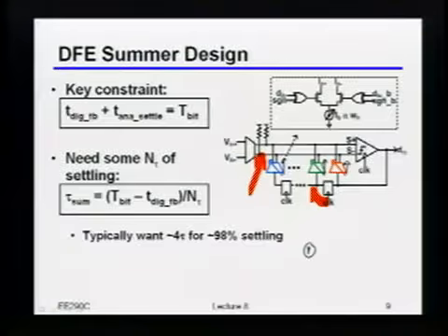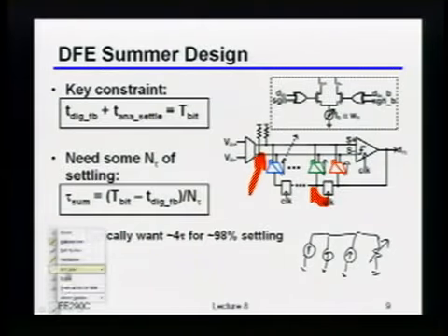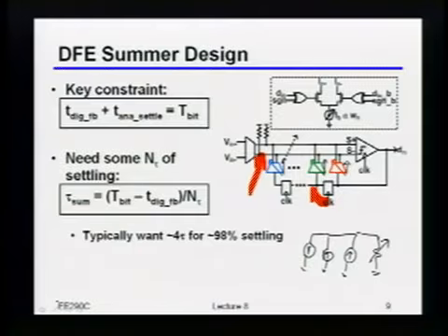So I can take all of those currents and dump them all into some node, but all that nonlinearity is doing is modulating that resistance, right? In other words, the addition itself, because that's all happening in the current domain, is linear. The only thing that's nonlinear is converting it to voltage afterwards, which means that the coefficients are also actually correct.